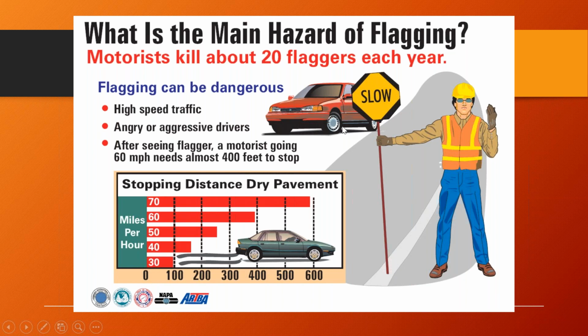So that's a good reason why we have our 500-foot spacing requirements on our advanced warning area, and the space between the last sign, the flagger symbol sign, and the flagger is 500 feet as well.